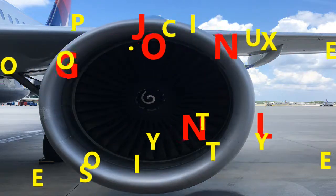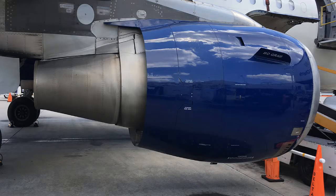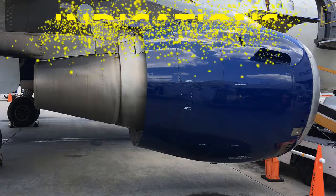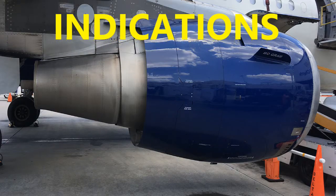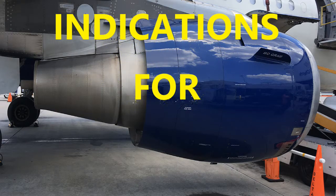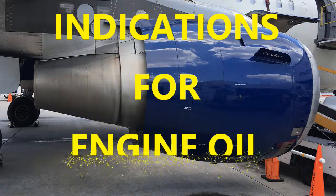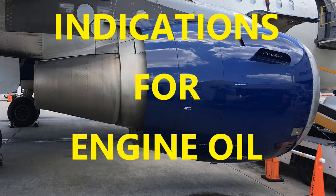And since we're going to be working and talking about it, or you're going to be working on it and I'm going to be talking about it, indications related to oil. Okay, remember what I said about quantity? We want to make sure there's enough oil in the tank. The oil tank, by the way, is located on the fan case of the engine at the 8 o'clock position. So there you have your typical sight glass to see where the level is as far as the oil in the tank.